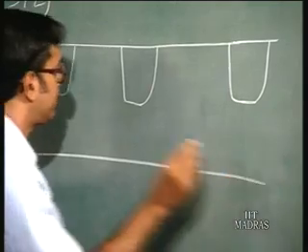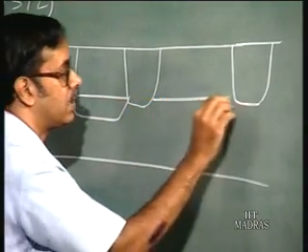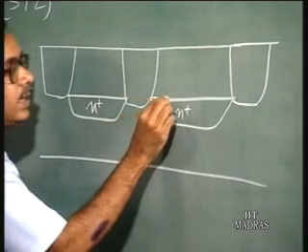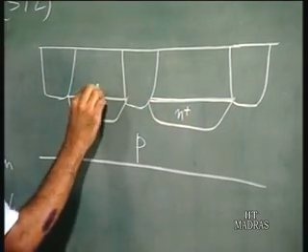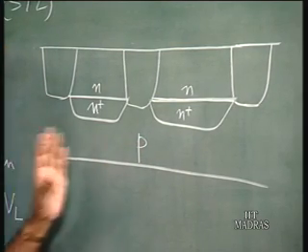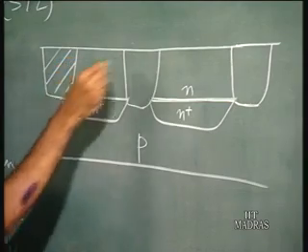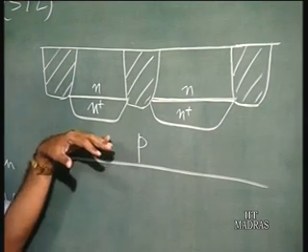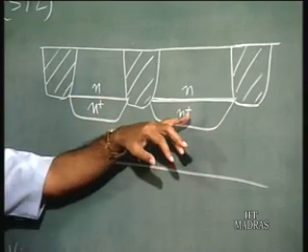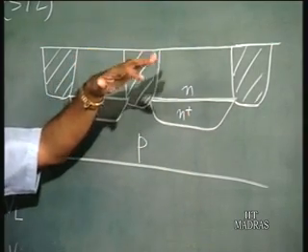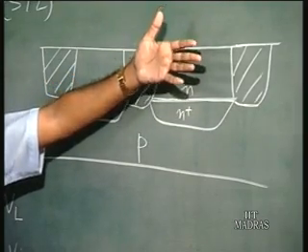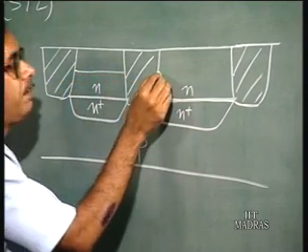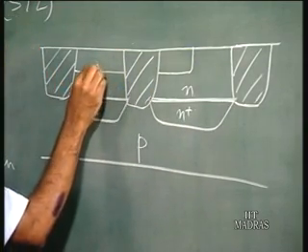So, what you have is again like a bipolar junction transistor, the starting wafer. You have a p-type substrate, and as we have seen in a normal bipolar junction transistor, this is the buried collector, and this is N. So, that is the normal bipolar junction transistor, and this is silicon dioxide, which is used for isolation. Like a bipolar transistor, you start with a p-type substrate, make the buried collector, and then you grow the epitaxial N region, where you actually make the bipolar transistor. Then you make the oxide isolation, then you have the base region P. So, this is the base P region.